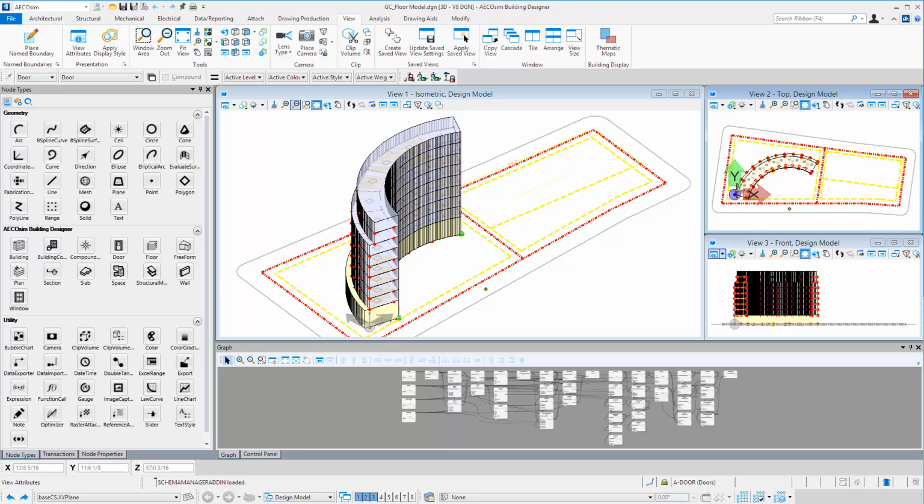In this arc, we're going to create tangent to the two sides of our building and connect the two endpoints. We also want to create this arc up at the first guest room floor, as it'll be a canopy above our lobby area. So once we create the arc, we'll use our slab node and create an actual building object, a slab that will be the canopy,